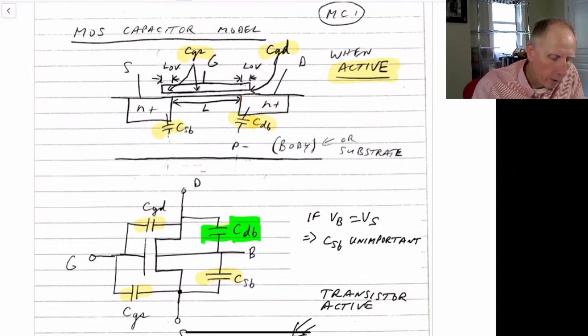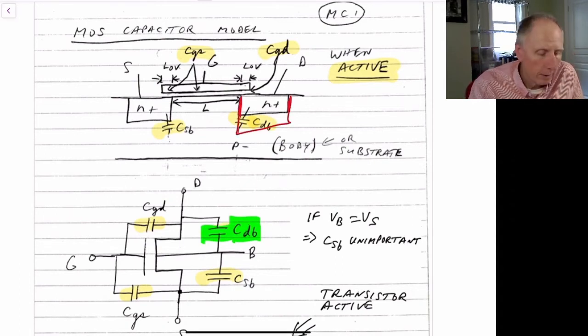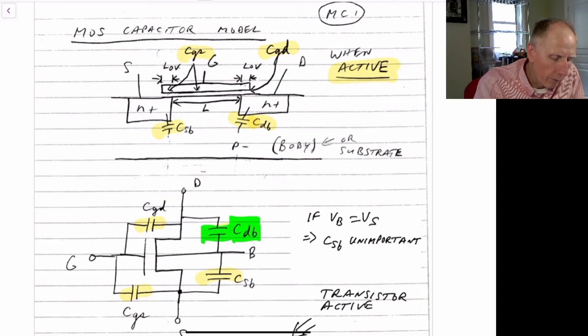So the total area that we see there will be our drain to bulk. Now, when we're building this, the distance that we go down here is not something we can control, but that is part of the capacitance that we have to worry about. If it went much deeper, it would cause more capacitance. But that's set by the foundry or the technology itself. What we do have control over is how far we build this out.